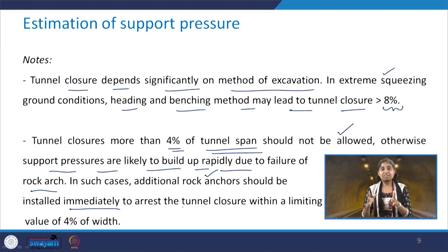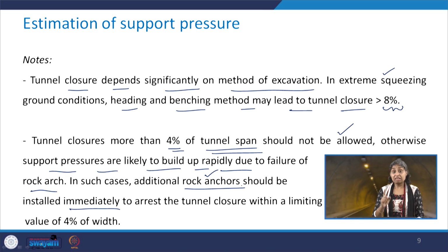So we need to be careful that in case we have the extreme squeezing ground condition, and if you are going for heading and benching method of excavation, then the tunnel closure can be as high as 8% or even more than that, but this should not exceed 4% of the tunnel span. So in order to restrict that, we need to provide the additional rock anchors immediately after the excavation of the